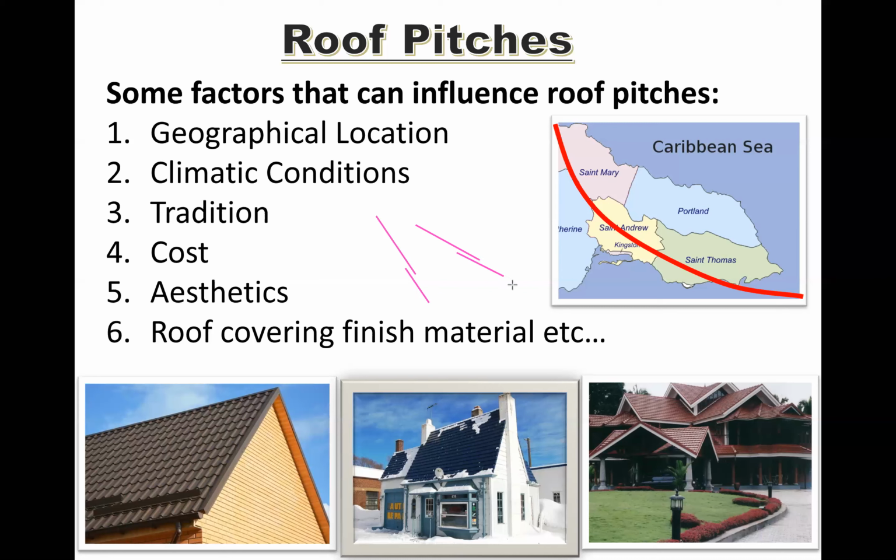The reason for that is if the wind is blowing and the rain is falling, then you don't want it to push that water up underneath the lap and then it leaks. But if it is steeper, then it will not travel so far up unless you have some heavy wind. But you would not just make it very short anyway. You could reduce the length of your lap and be able to use less shingle to cover your roof. But if you're going to make it shallow, then you would have to increase that lap so that you compensate for the leaking.